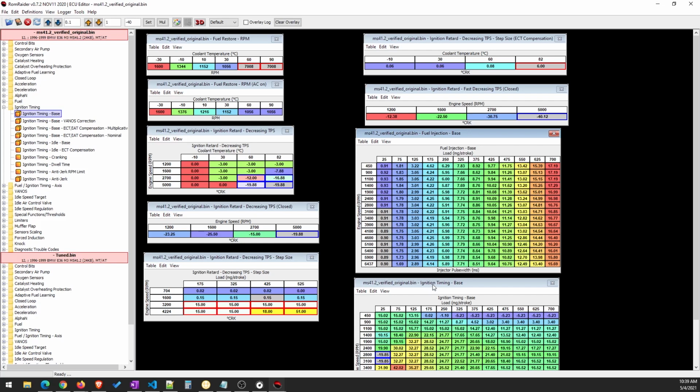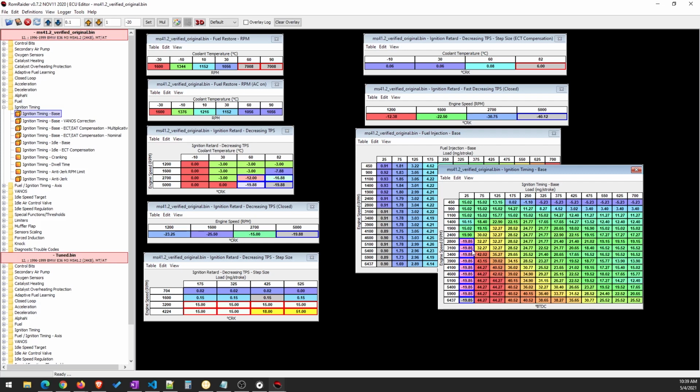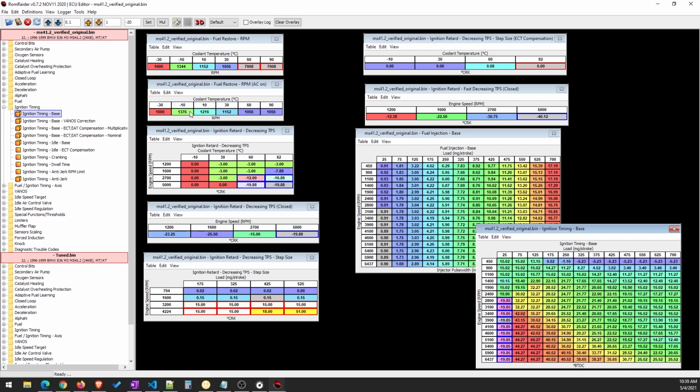And then likewise, in this table, this is your ignition timing. So similar to the changes that we made for the launch control, you would basically max this out to -20 degrees of timing all the way across the board. And again, if you want a less aggressive burble here, you would change these values to, let's say, -10 for a mild burble.